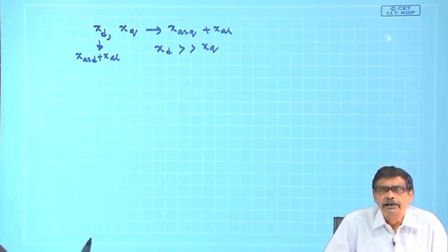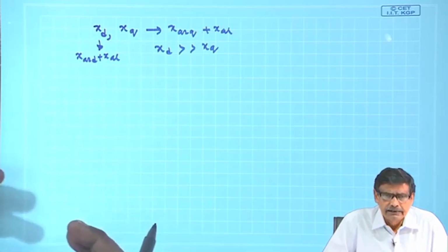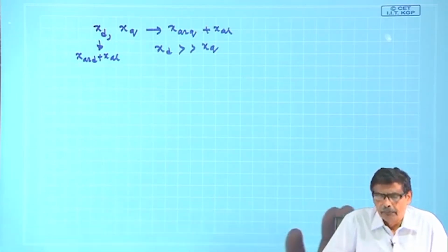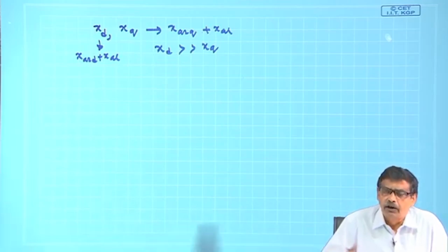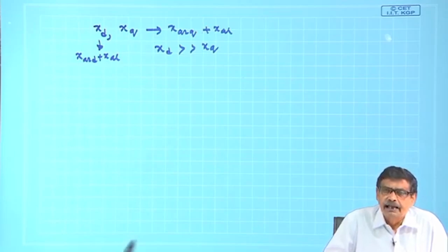I must be provided with the information whether the machine is operating in generator mode or motor mode. That is one piece of information. Also whether the generator is operating at lagging power factor and how much current it is supplying. So, IA, theta and terminal voltage will be known, and then you can draw the phasor diagram.